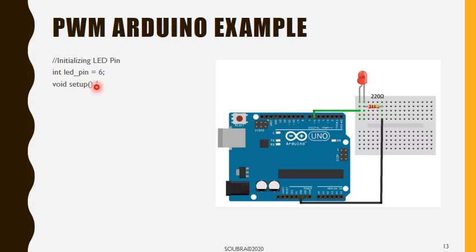Well, the loop is perpetual, so it goes on as long as your system is under power. First and more importantly, I'm using a general input/output pin here, so I need to define its direction, whether it's an input or an output. Here we're defining pin number 6 to be an output, of course, because I'm connecting an actuator to it. Fair enough.